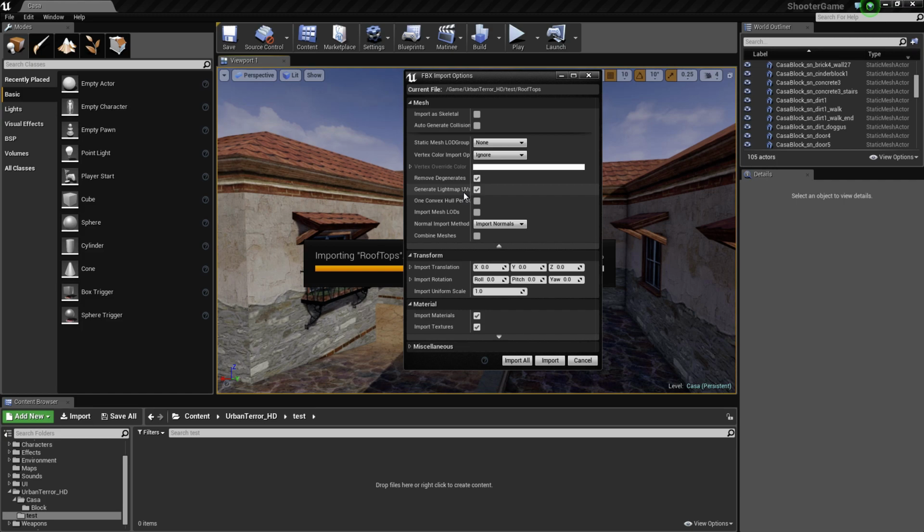It was a time-intensive process that is not really necessary. So when we do an import, the option you probably want for bringing in one big block is to generate UV mappings for the various items that you bring in.